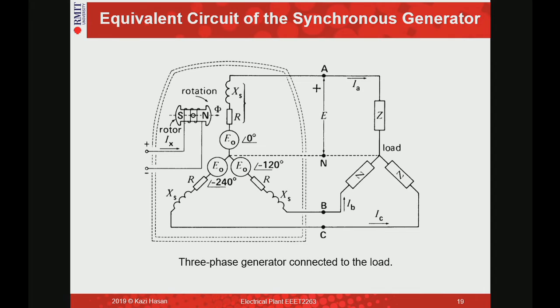So this is the representation of a three-phase synchronous machine in a power system. This box is actually your synchronous machine. What we have drawn in the circle was the mechanical structure. If you want to represent it electrically, it will look like this in the equivalent circuit. We have drawn three-phase A, B, C voltages. These are the generated voltages in the machine, E naught.